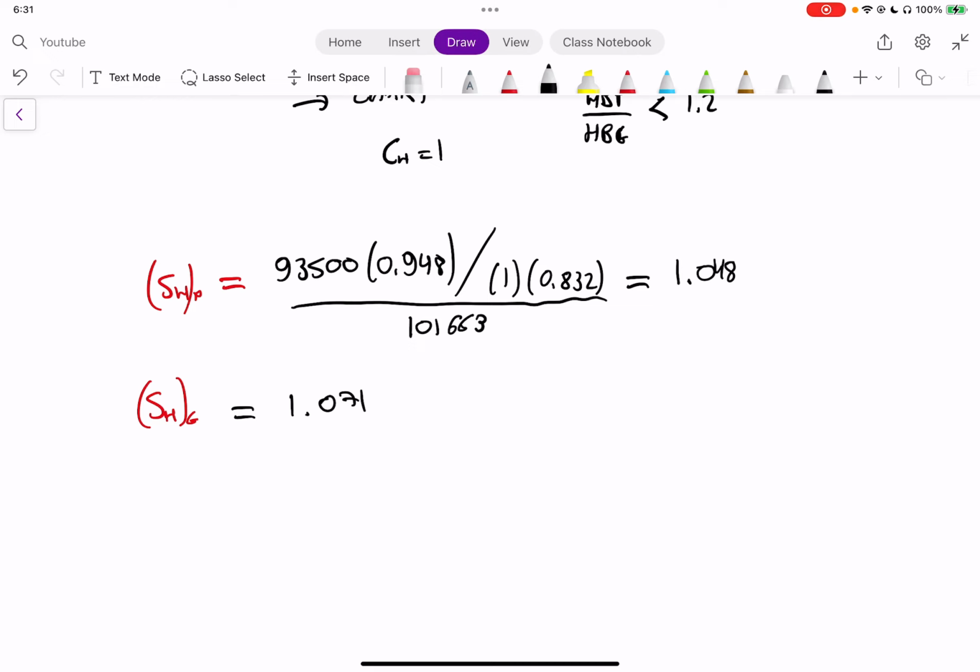Well, we see that this is very close to failing. So even though we were just asked to find the 4 safety factors and that's it, we definitely want to make sure that we would redesign the system with a higher safety factor. Okay, so we need either more strength in the gear, or we need to modify something about our system to increase the safety factors.